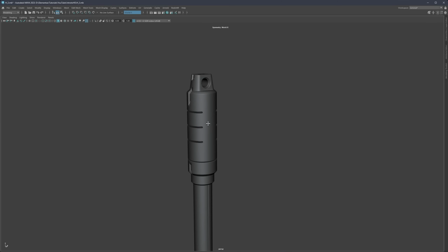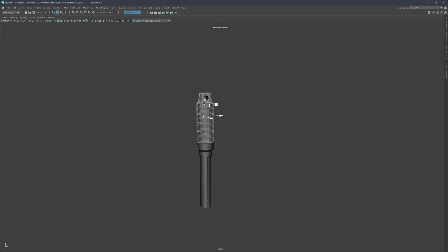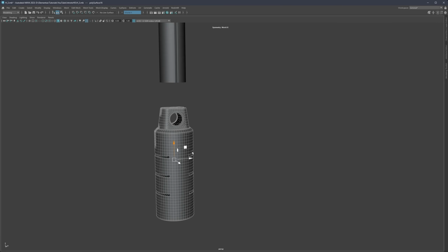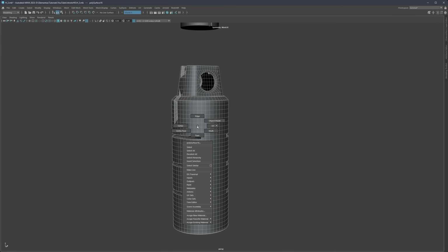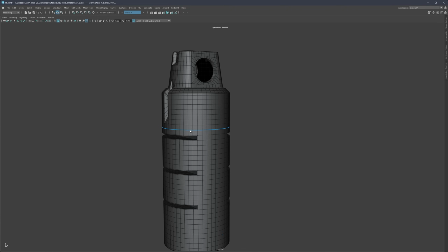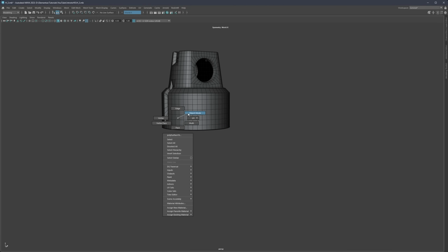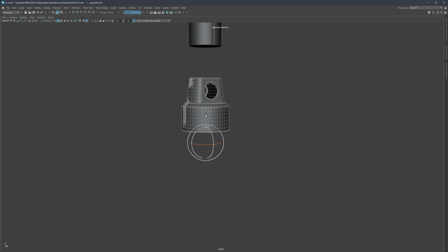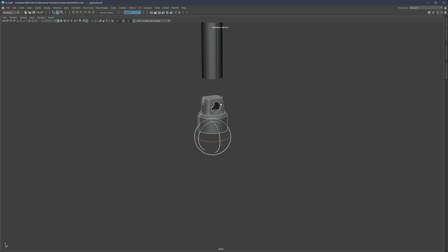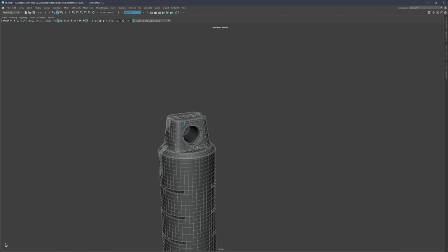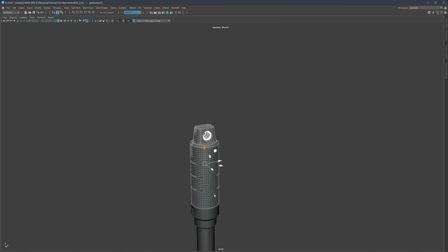All right, so now what we can do is actually copy this from the top to the bottom. And let's go to move, clone, and push it down. And the thing is, I don't need everything. I just need, let's say, edge till here. So let's go to detach components, face mode, and delete this. And let's go to object mode. We're gonna need to rotate this. And also notice one thing, I didn't now copied everything, so I just need to be sure that I'm also copying this inner part as well.